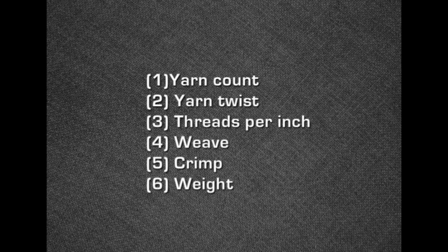All these factors can be varied in either warp or weft direction, and the problem of predicting the mechanical behavior of these fabric structures may become complex, as some of the factors which we have just mentioned may be independent, while others are related either throughout their ranges or merely at their limits.